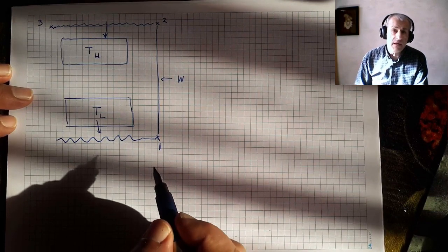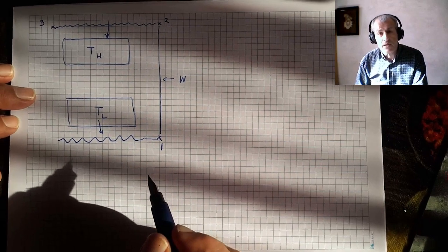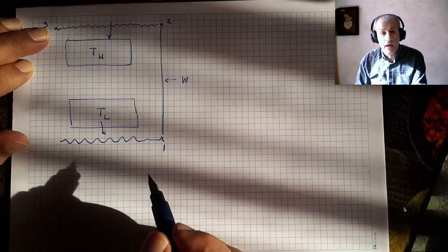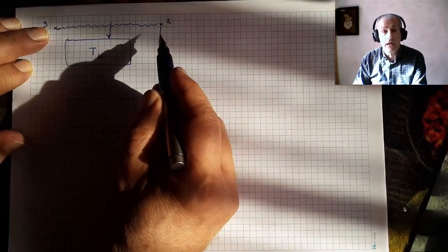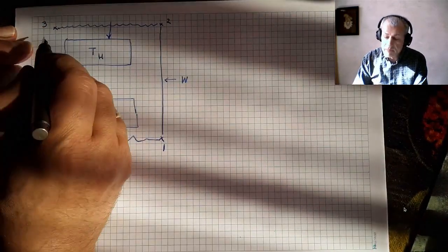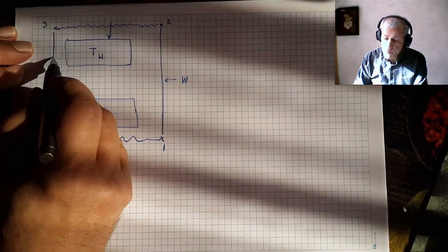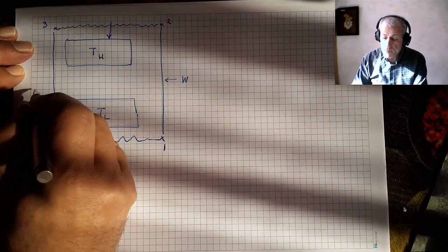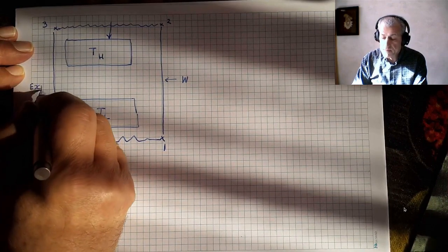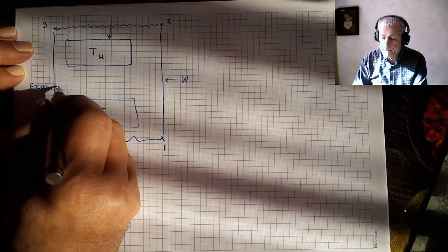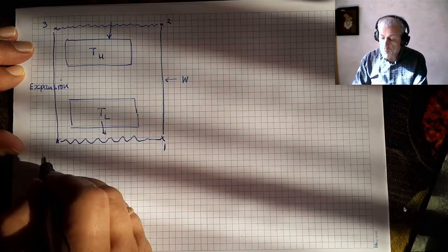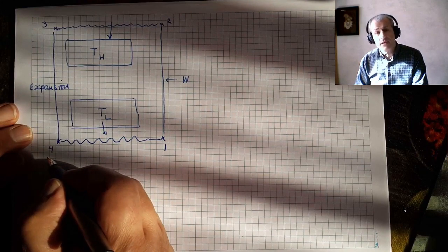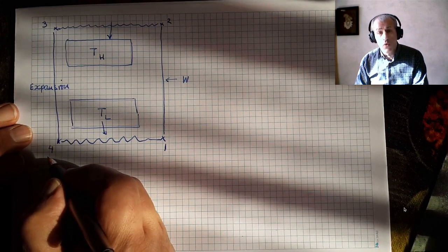So your medium has cooled down due to heat transfer to the high temperature reservoir. And finally, the key process is the throttling process. You have a cold medium, and your cold medium has high pressure. You expand it. This is expansion to a point 4 to a lower temperature, and this expansion produces low temperature.